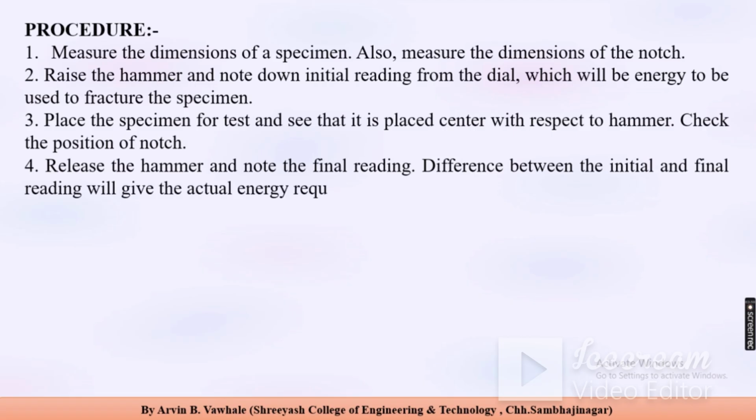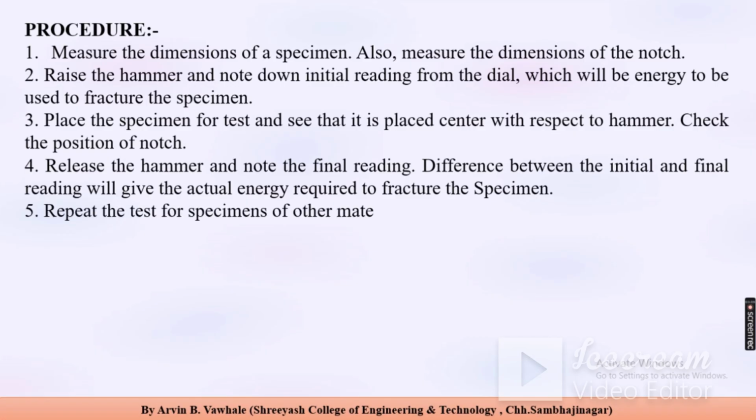The difference between the initial and final reading will give the actual energy required to fracture the specimen. 5. Repeat the test for specimens of other materials. 6. Compute the energy of rupture of each specimen.